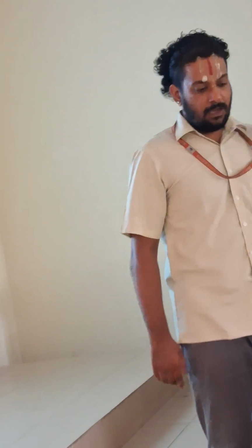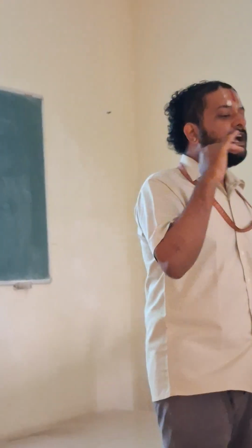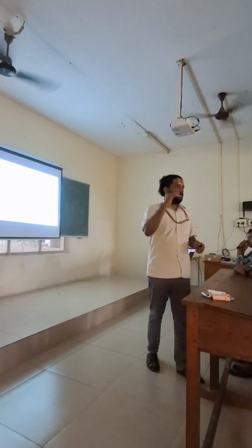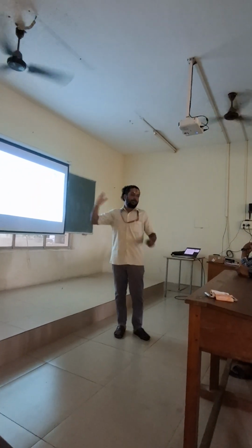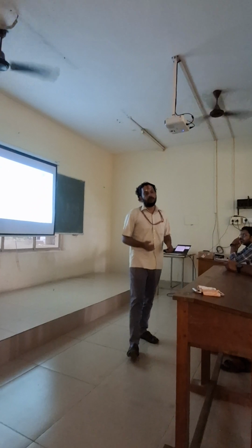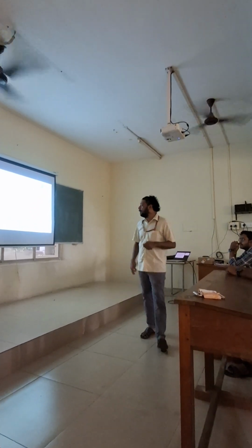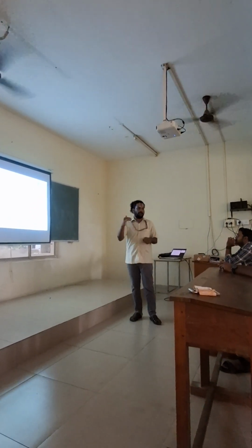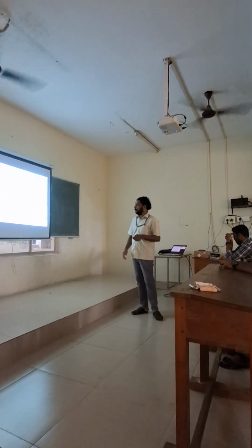Let's say these are what is known as the quasi-Fermi level approximation. We have a non-equilibrium system where we cannot really define what a Fermi level is. A Fermi level is supposed to be the level of equilibrium at which at least half of these states are occupied. So once we attain non-equilibrium, we cannot define a Fermi level, which we generally use as a reference state to calculate much of our electron transport problems.